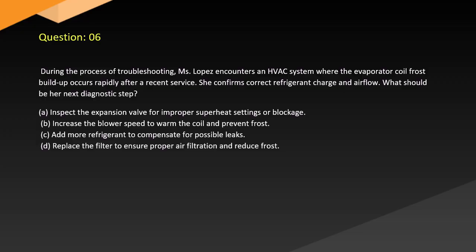A. Inspect the expansion valve for improper superheat settings or blockage. B. Increase the blower speed to warm the coil and prevent frost. C. Add more refrigerant to compensate for possible leaks. D. Replace the filter to ensure proper air filtration and reduce frost.